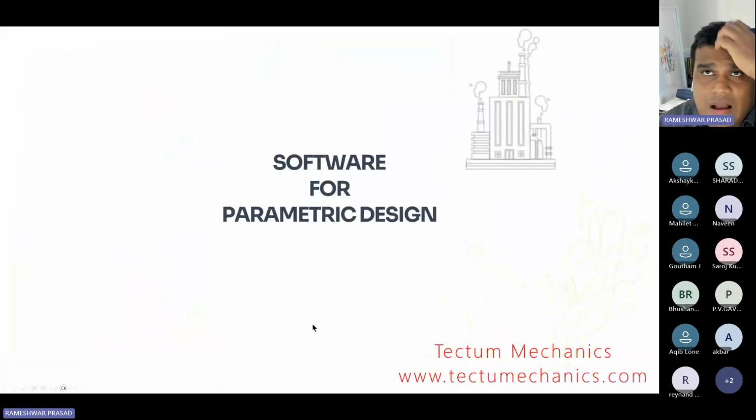Okay, now I didn't touch much upon design because the analysis and geometry essentially define it. If you want to, you can do optimization based on profile sizes. You can do optimization based on the reinforcement. Although SAP2000 has a very crude way of calculating reinforcement, that's why I don't use it. But you can write your own program in a computational design software, which computes the reinforcement based on the bending moment generated, and then you can link it to your optimization algorithm, and it will keep on changing the depth for a particular reinforcement size and spacing if you want to.